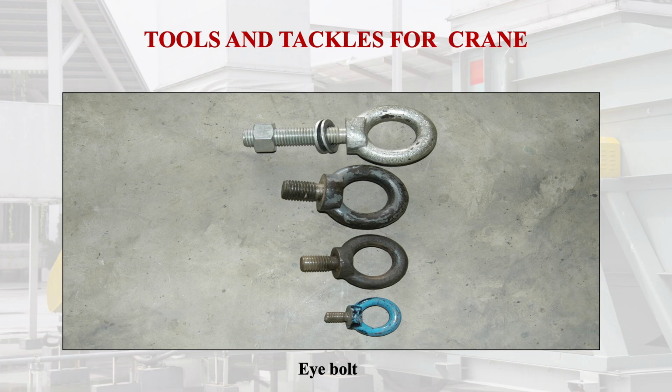Apart from this, we should also see whether the diameter of this shackle is still circular or it is becoming D-shaped. If it is D-shaped, then we should be cautious that it may fail to perform in a safe manner.